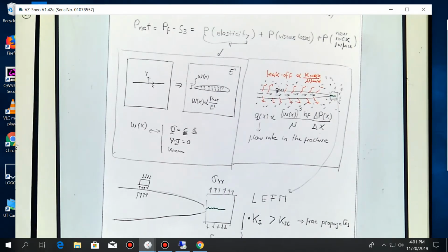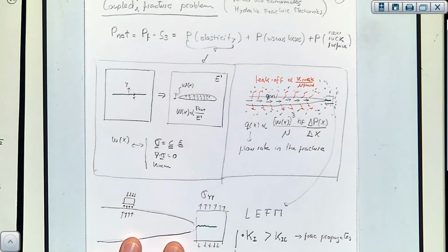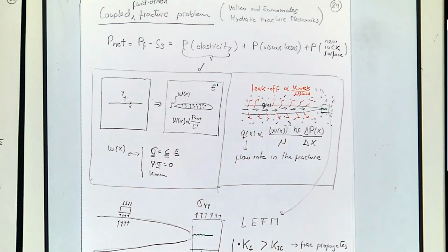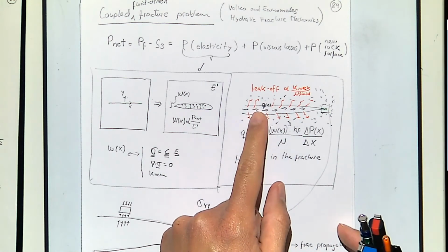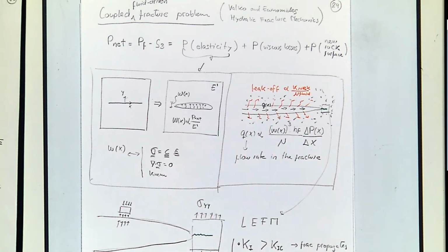The last thing that we saw was about how to understand a little bit better a problem of a fluid-driven fracture. And this is not just some sort of open mode fracture that just includes mechanics, but here we have also the influence of a fluid that is opening the fracture and it's exerting a pressure and that transforms into a stress on the wall of the wellbore.